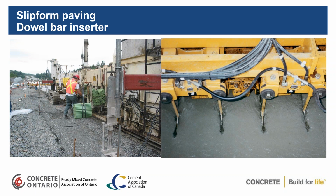Because this is a very stiff mix again, the 0.42, maybe down at 0.4, these dowels will stay exactly where they're vibrated to. The vibration process allows the concrete to totally flow around it so that there's no gaps over the top or in the bottom of the dowels. Very efficient, fast process, saves a lot of manpower in trying to place the dowels themselves.